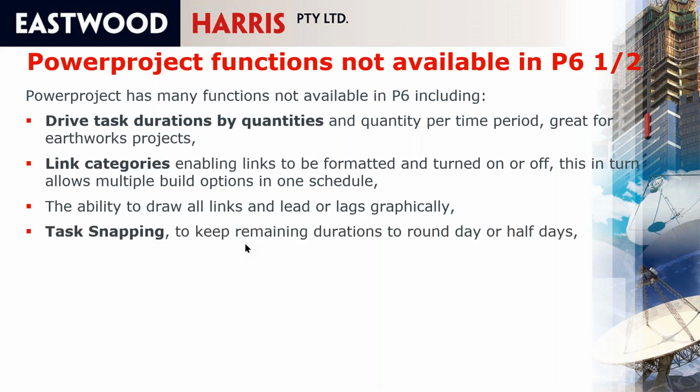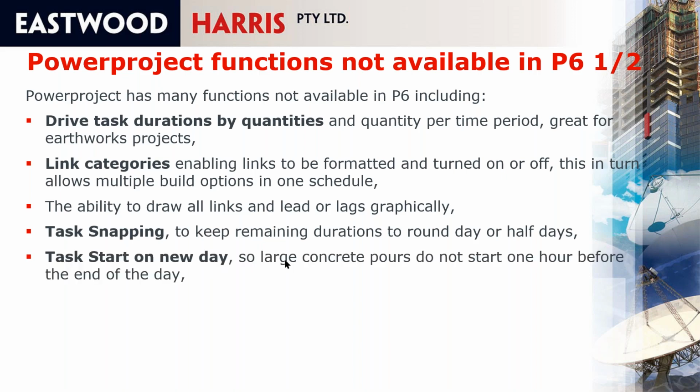It has task snapping to keep durations to a day or half day. And again, it's very easy in P6 and Project to end up with durations in decimals, you know, 0.11 of a day remaining, things like that. It has a start on new day function to stop concrete pours starting late in the afternoon. It has the ability to reschedule part of a project, so you can be working on part of a project, just reschedule that part, and not destroy the rest of the program.